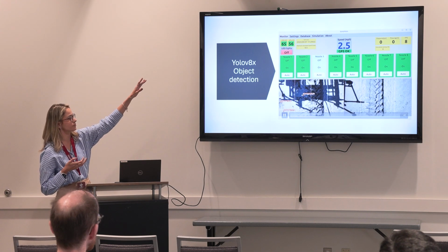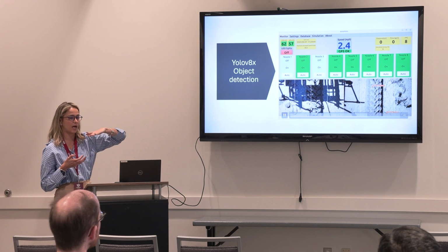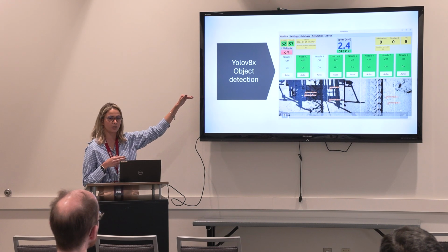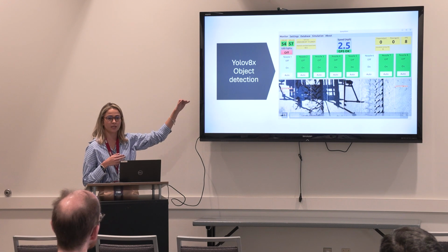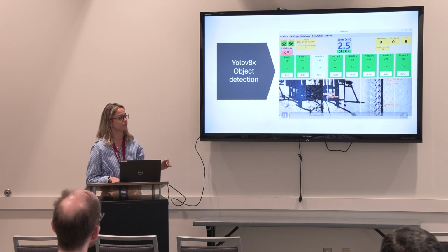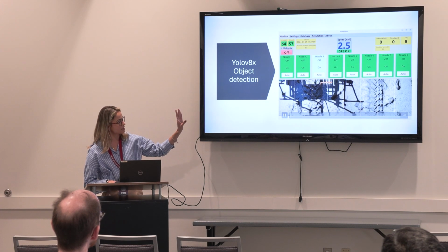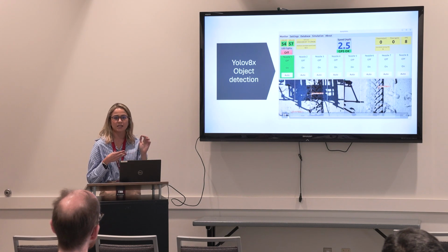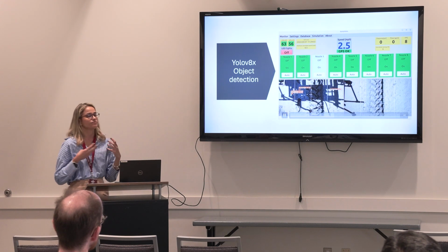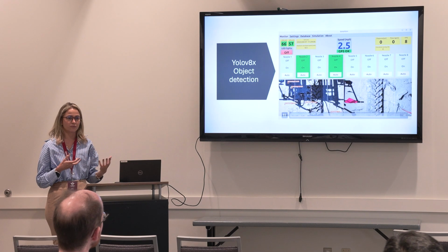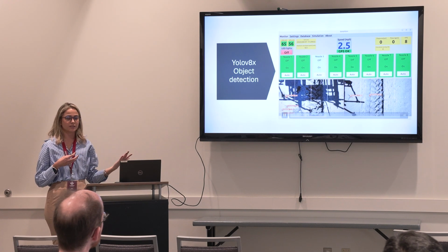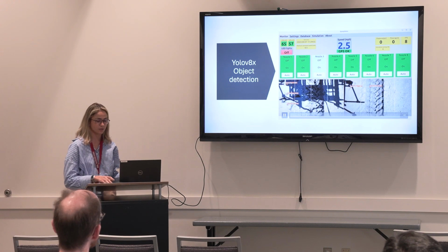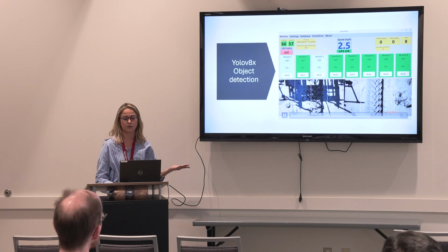And you also have other things on the controller, but especially when I'm applying, off is used when I don't have to spray anything. On is when I want the broadcast method application, and auto is when I want the model working in detecting the weeds. As you can see, using the bounding boxes, this time I was able to identify what is a broadleaf, what is a nutsedge, and what is a grass. But for the calculations of precision, recall, and everything, you do not discriminate these weeds, because in the end I'm applying herbicide for everything at the same time, so I'm not using different herbicides for each category of weed.